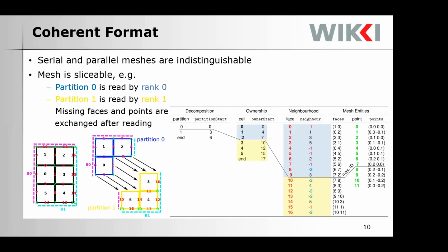Okay, of course, that's a good question. You're talking about this one. So this one was run on, you still need to run a decomposer to get a nice decomposition, right? Because if you run it from blockMesh, you can still start your MPI run. It will be read, but the decomposition will be ugly. It will be something separated into corners. You still need a renumbering or resorting method to get a nice decomposition.